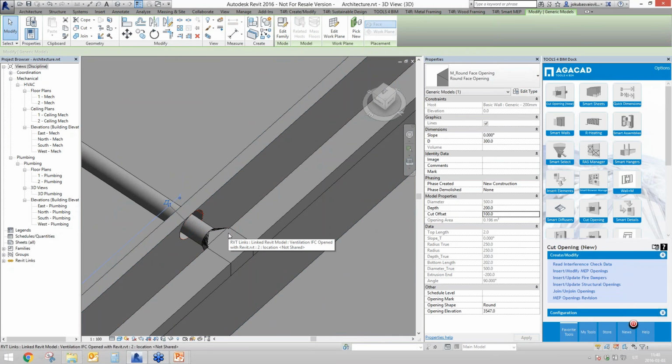Right now we are going to build a new possibility to export the current situation. For example, you will make openings, move everything, and then export the opening shape, opening width, height, etc., and opening position, and send that XML file to the architect or the structural engineer. I'm talking from the MEP engineer side.